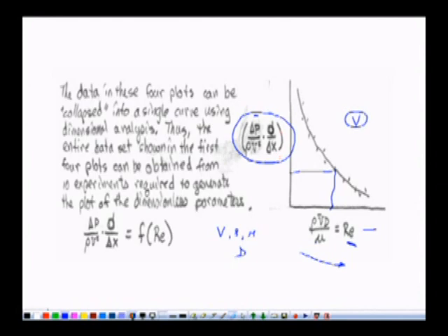Now, we know diameter, we know rho, we know V square, we can find out del P over del x. Similarly, if we have a different diameter, or different viscosity, or different density, substitute here, get this Reynolds number, find out the corresponding value of this term through this graph, and calculate del P over delta x.